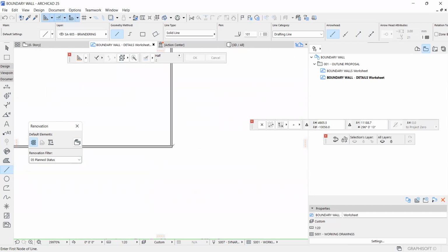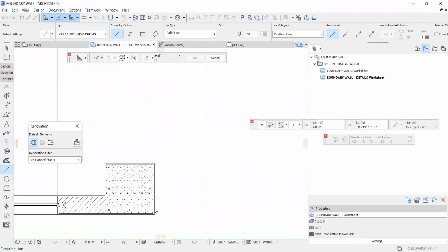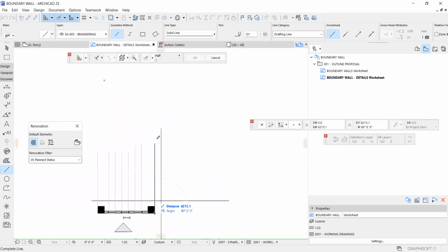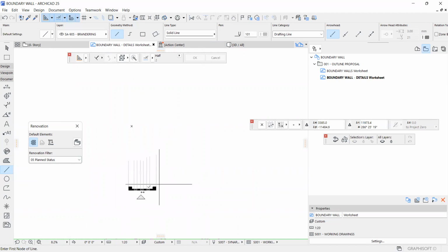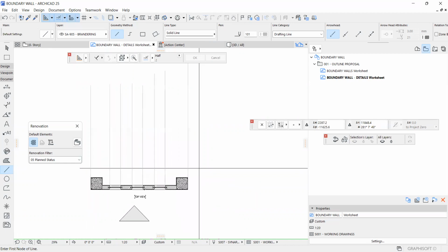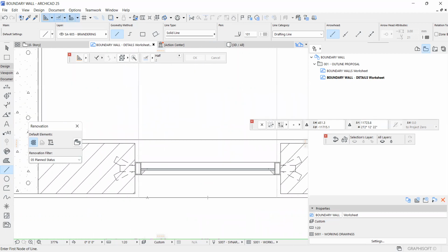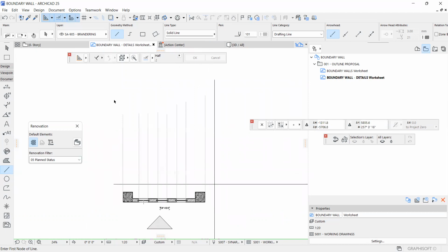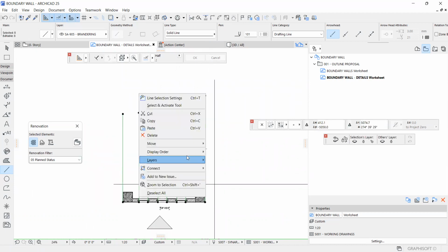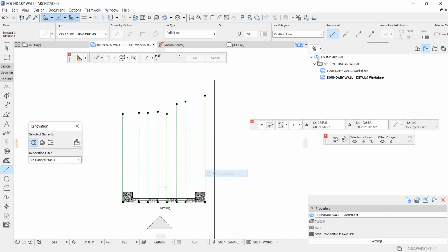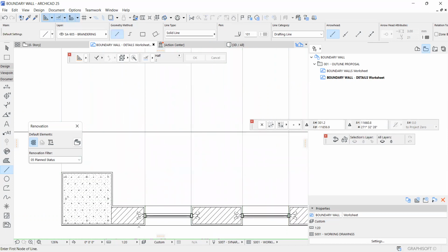Now in projecting, especially when doing manually, you use guidelines, a hard pencil, a 2H or its equivalent. And you just touch the sheet, okay? So up to that point, we have projected the corners, okay? In my case, I'll want to take the projected lines lower than the drawing so that it does not affect my original drawing, okay?